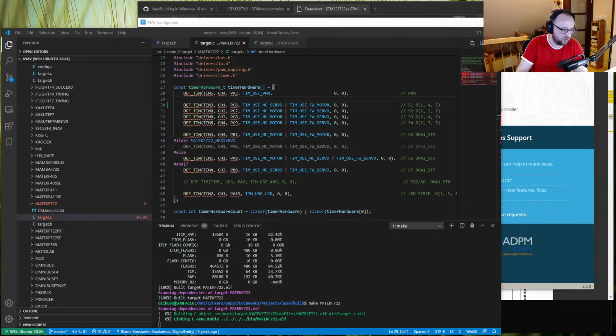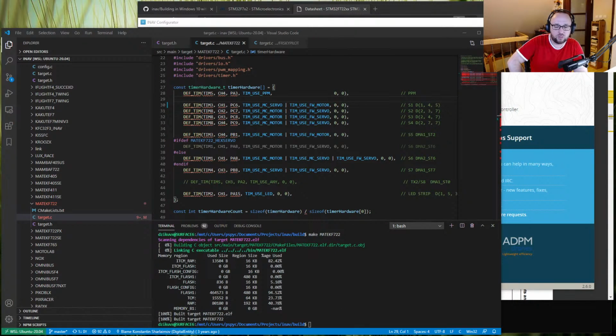Mike's Adventure has a question. Have I ever put a LiDAR sensor on a quad instead of the GPS? No, because it's not really instead. A LiDAR is only a device that can measure the distance from itself to the ground or any other obstacle. To have the optical flow, to keep the quad orientation based on the shapes on the ground, you need an optical flow sensor. There is this board from MATEK called the MATEK optical flow sensor. I have it over here on my PIRX 7. I have it configured, enabled, but I'm not really using it much because in the places where I'm flying, there are not enough patterns on the ground to be able to play with that.